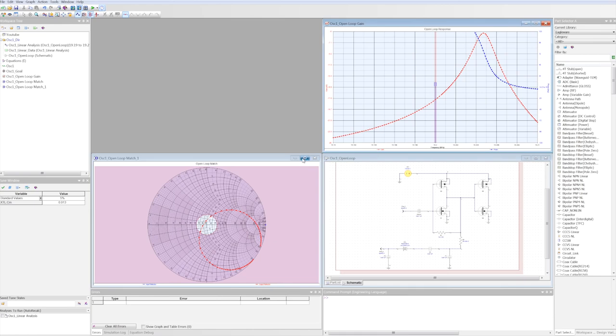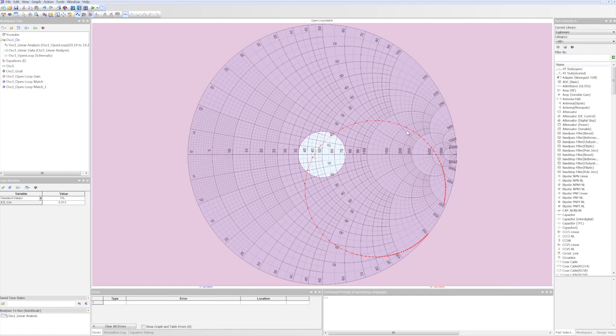And we can actually see that very clearly over here in this plot of the S22 and S21 parameters. So we see the output reflection, the reflected power from port 2 here in red, and you can really just barely see S11, which is the input reflection, the power reflected from port 1.